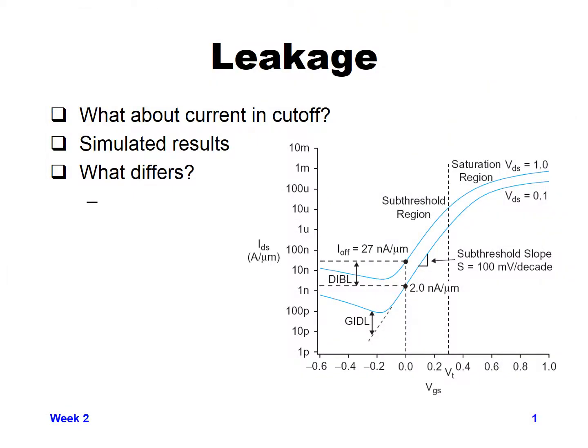So in the following section, we're going to be talking about some other non-idealities that you encounter in silicon process. Some of them will directly affect the transistors, others just affect things like leakage, for example, affect power consumption and how fast you can maybe switch something on and off, but not directly affect the transistors as far as our IV current characteristics. So one of the main non-idealities is we have leakage in our currents.